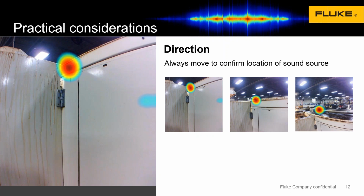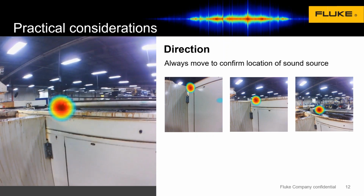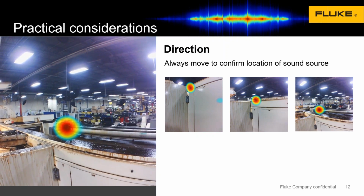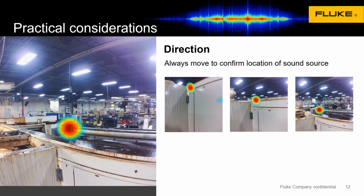And once again, I'd like to see you do this in the amount of time that we did with the acoustic imaging tool if you had a traditional ultrasonic device, or you were just trying to listen to the hiss with your ears. This was one of those leaks that we could not hear. This was full production time in this particular factory. There are plenty of other noises out there, and we were able to find this one and pull it out from everything else that's going on.